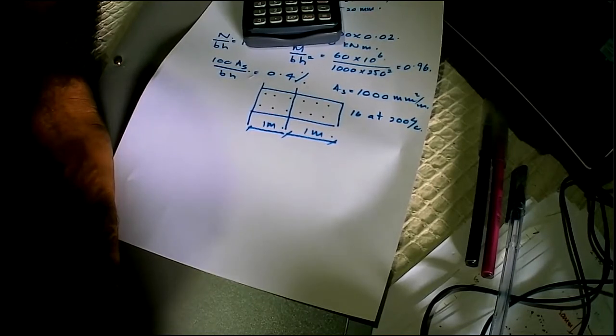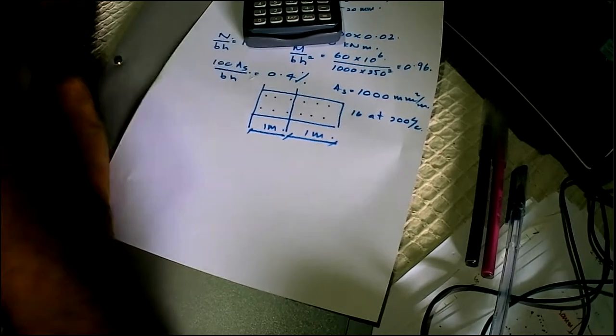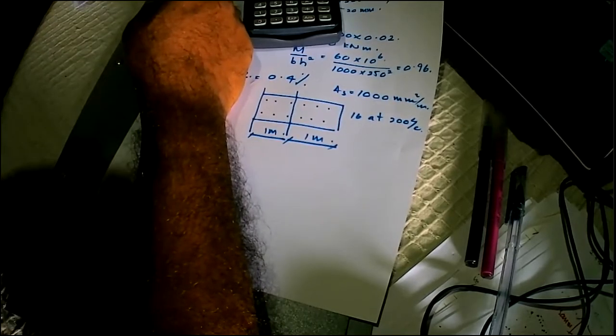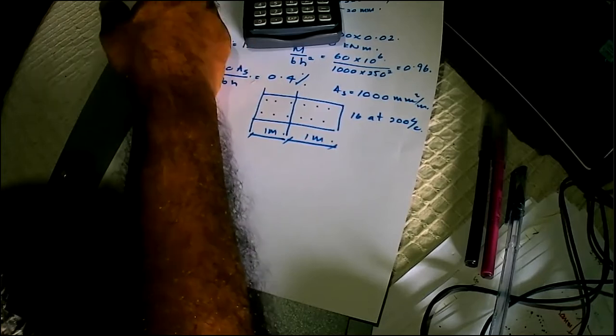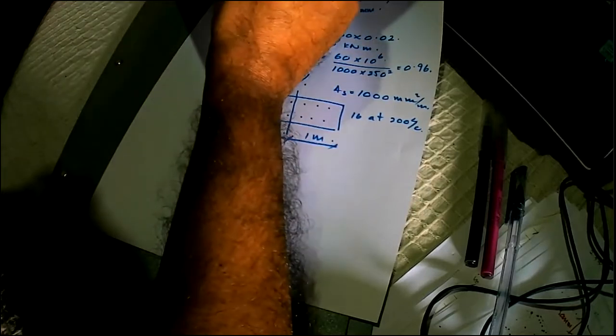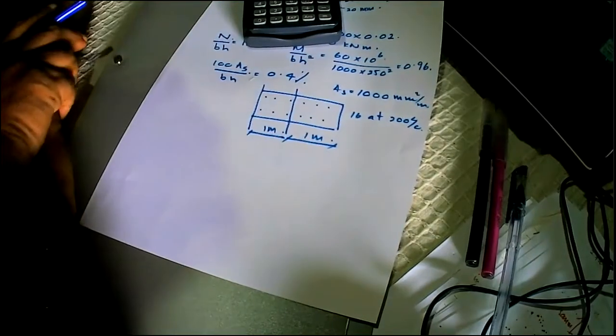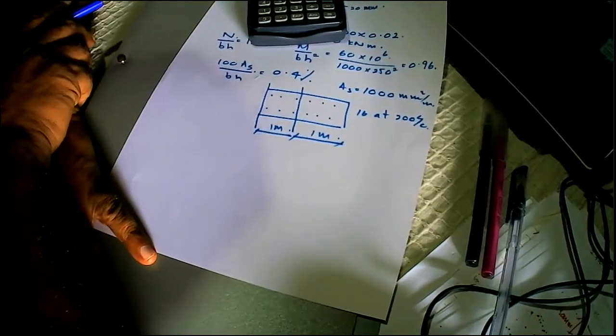So that's why these coupled shear walls are so important, because once you couple the shear walls, the bending moments will reduce and the chances of tension occurring under the foundation can be reduced to a significant level. So basically you can ensure that no tension occurs under the foundation. Is that clear? We don't like tension in the foundation, no tension in the shear wall.